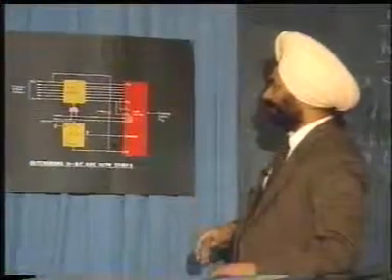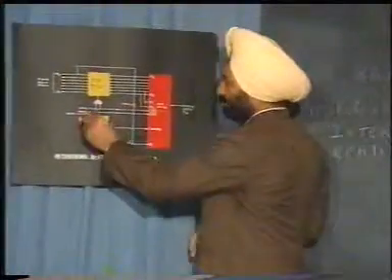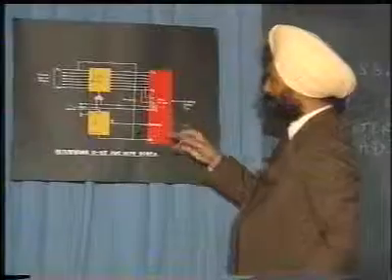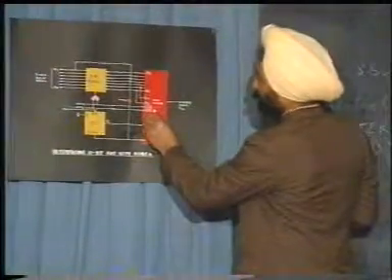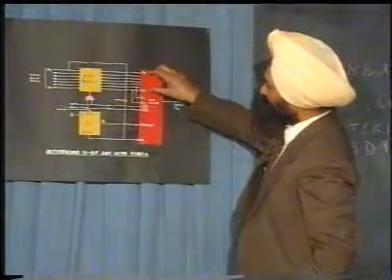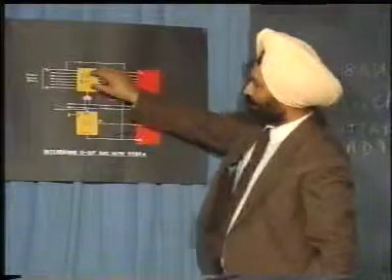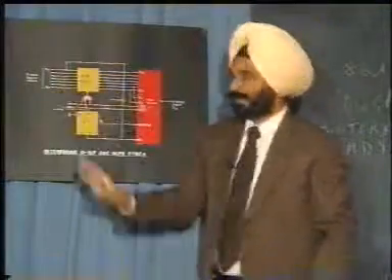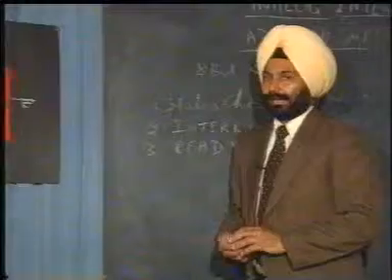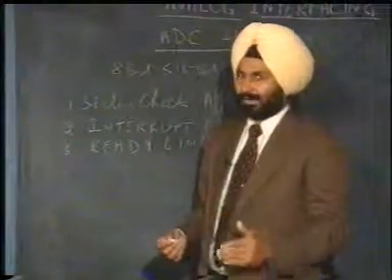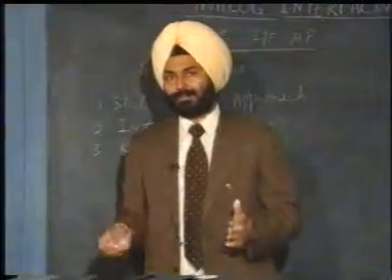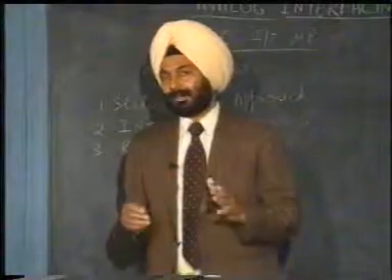Then the microprocessor enables port 3, which enables the HBE bar signal, which allows the next 8 bits, D2 to D9, to be read through the buffer, again enabled by this. So like this, an A to D converter up to the width of 16 bits can be interfaced.